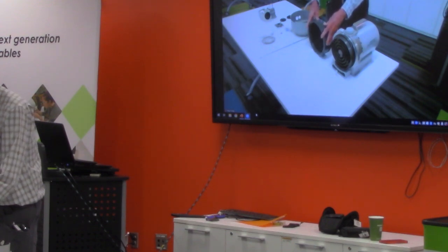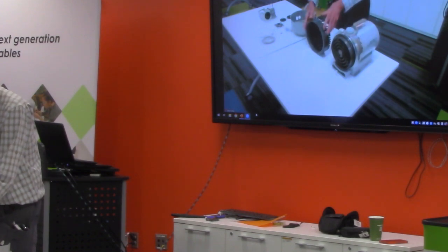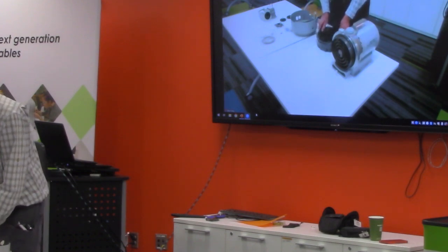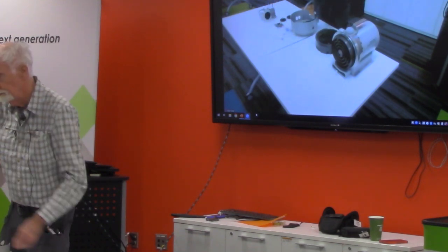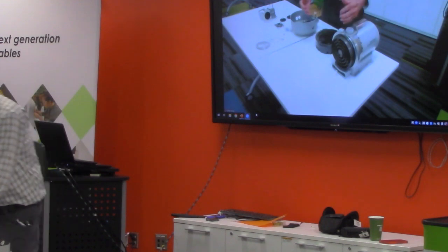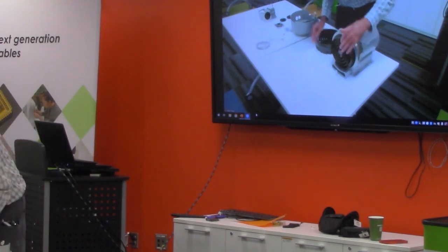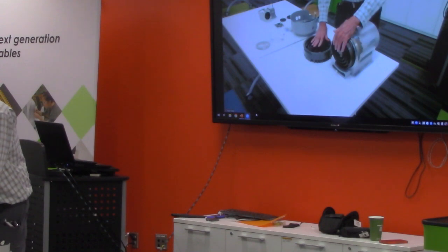Okay. And if you buy a new analytical system from somebody, or you're buying an MOCVD system, I'm pretty sure you're not going to have an oil pump on it. So it's worth understanding this. What is interesting with it is the tip seal. So after a while, this is very precisely tightened so that the surfaces are just touching.